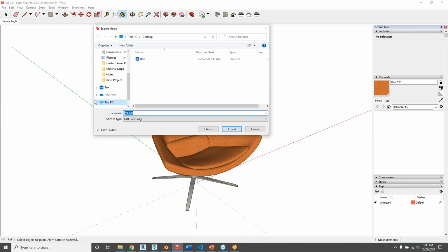We've got a bunch of options here. We could do OBJ or we could do FBX. I typically go with OBJ because I find, in SketchUp at least, you will notice that it gets a lot slower to import and export OBJs when you have large models, let's say over 40,000 polygons. That is probably larger than what you want to use to create an asset anyway. So if your OBJ is taking a really long time to export, maybe take that as a cue that the model might be a little bit too heavy.